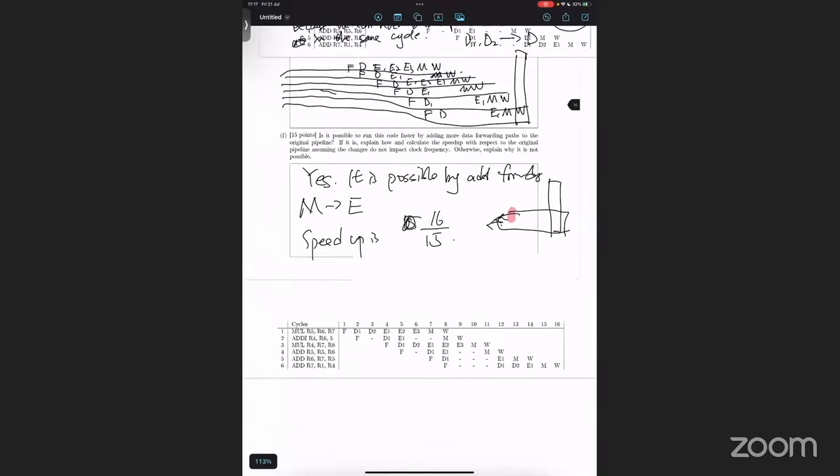So you're referring to the original pipeline diagram, right? Can you say again, which instruction are you looking at? Yeah, instruction 2. We are finished with the execute stage because it's an add instruction. But then we have to wait 2 cycles. Yes. It's because it's an in-order pipeline. So you have to wait before the previous instruction has released the stage you need next. Okay, thank you. No worries.